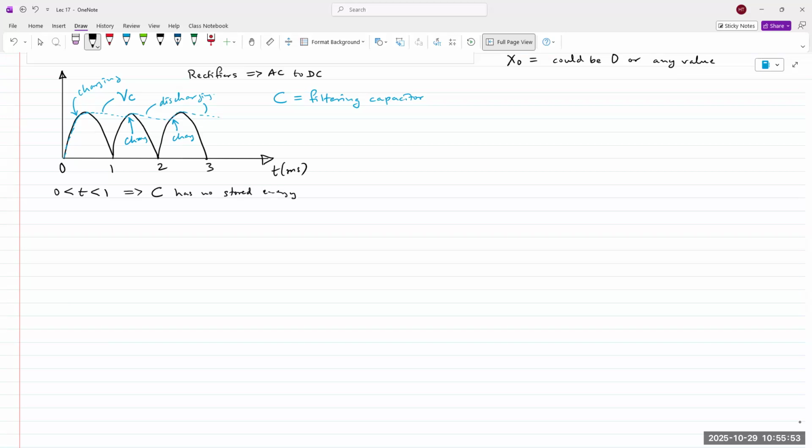Now you flip the switch on, power is applied to the system. Within 1 millisecond or half a millisecond, let's say it reaches full charge. So for the first time period, if I had to write an equation for the transient response, I would say X0 is 0 volts. My XF, or final value, let's just say 5 volts, random number, okay? My XF would be 5 volts.